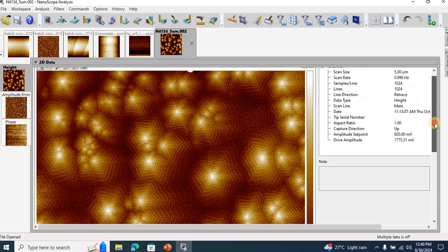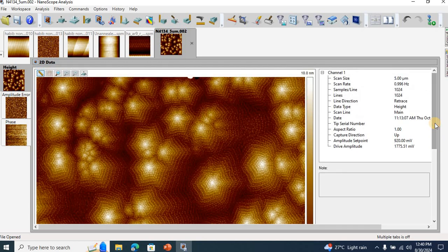and growing indium nitride films is not easy because we have to keep the substrate temperature really low. These films are grown around 350 degrees C, and the dissociation temperature of indium nitride is 650 degrees C. So at high temperature you want to grow high quality films, while at the same time the metal from your surface is evaporating. So it's not easy to grow high quality indium nitride films.